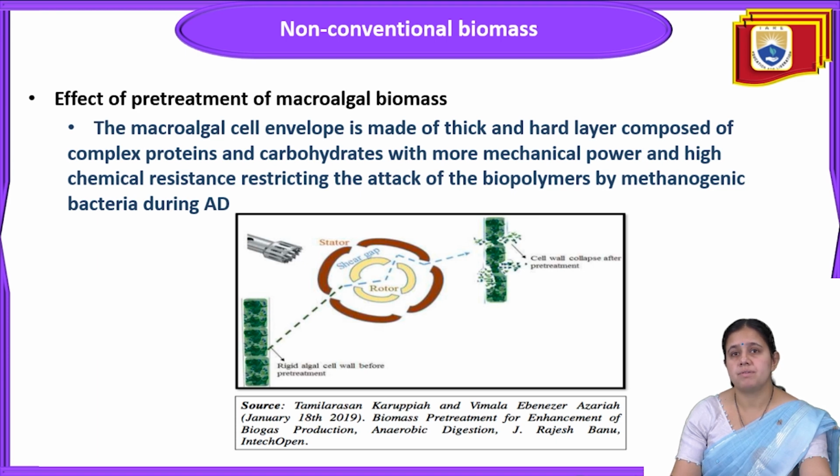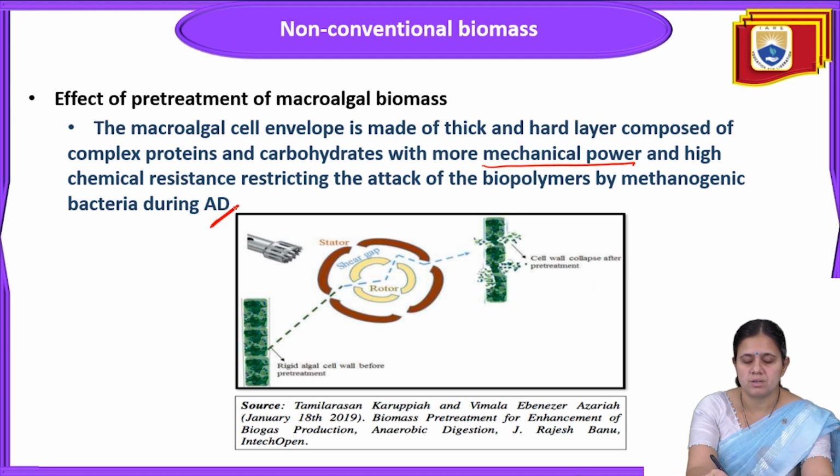And the effects of pre-treatment of microalgae. So what happens in this pre-treatment of microalgae? The microalgal cell envelope is made up of a thick and hard layer composed of complex proteins and carbohydrate, with high mechanical strength and high chemical resistance, restricting the attack of biopolymer by methanogenic bacteria during anaerobic digestion.